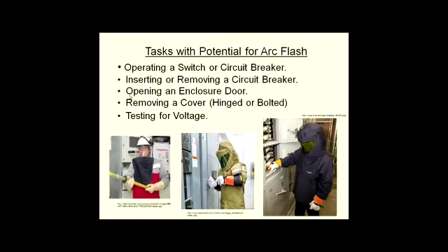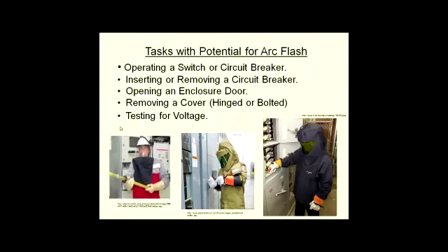Here this gentleman is opening the enclosure door to gain access to electrical circuitry. That can cause an arc flash because some elements could detach and fall into some parts, and that could cause an arc flash. So there is a potential for arc flash.